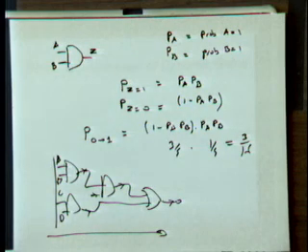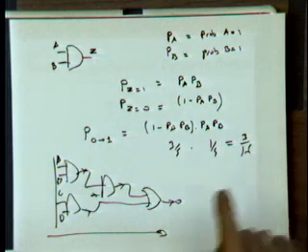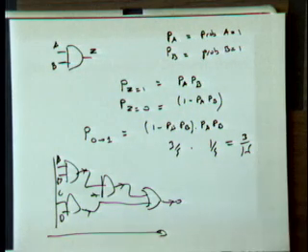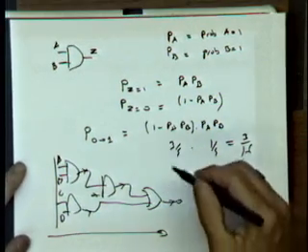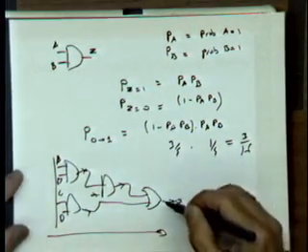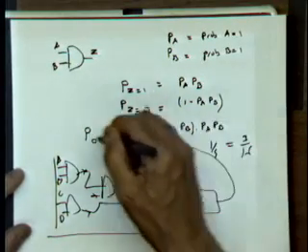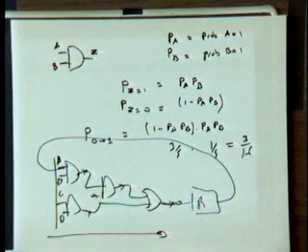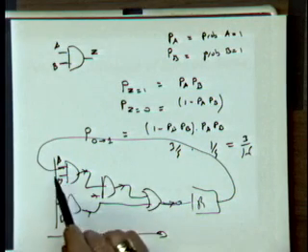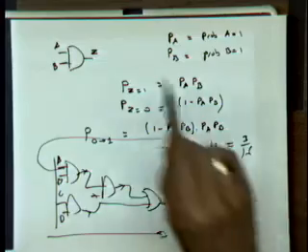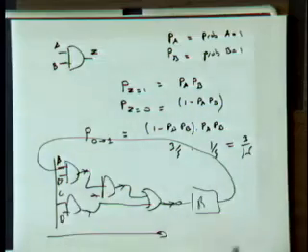There are a few caveats. There are 2 caveats that are very important. Number 1, which is not a problem for the project, you didn't have that problem in there. But very often in sequential logic, the output of this thing goes into a register, and this register goes back into the inputs. Now you see that the probability of A is not known. It's basically a function of the network, and it feeds back. I have a loop. So you cannot really work from the beginning to the end because you have to iterate over it a bunch of times. That takes some time, but you can do that. You iterate over it, and finally you find some probability.